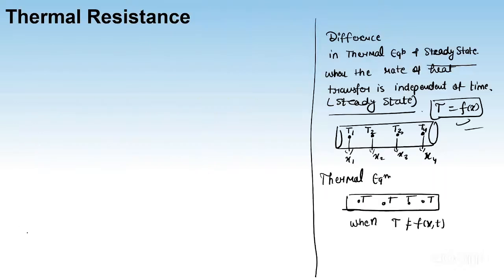यहां से मेरे पास इक्वेशन बनी थी that rate of heat transfer, which is H, nothing but dQ by dt, is equals to kA dT by dx. ठीक है, and it will be negative always because rate of heat transfer होगा higher temperature से lower temperature तक. ठीक है.